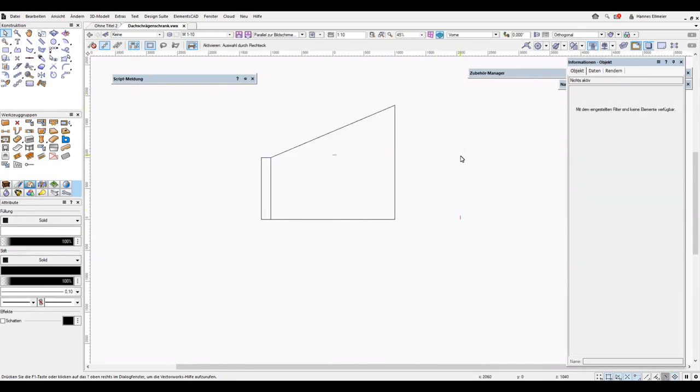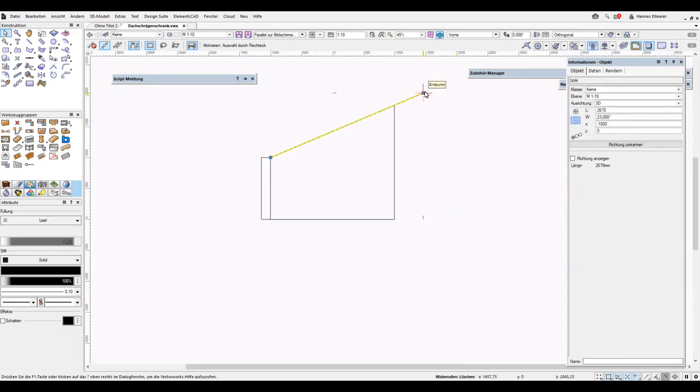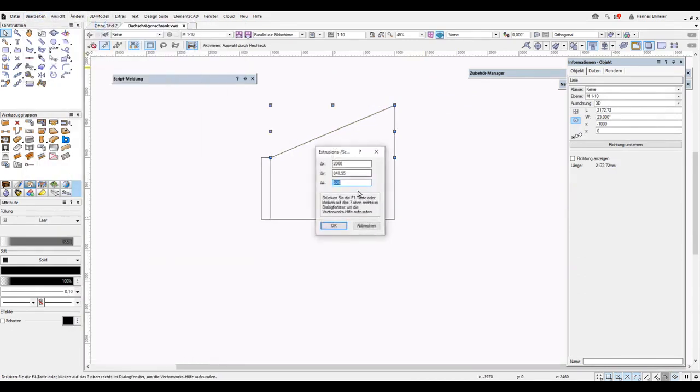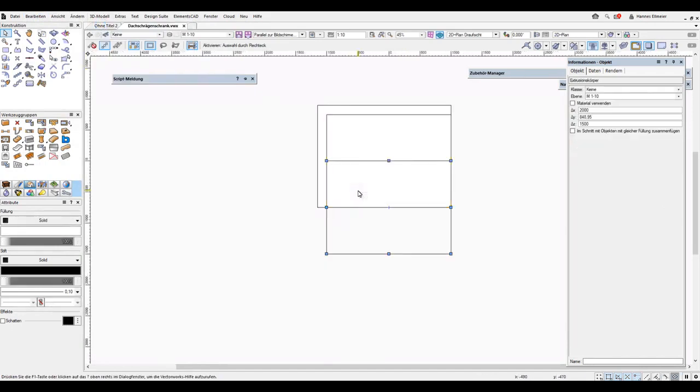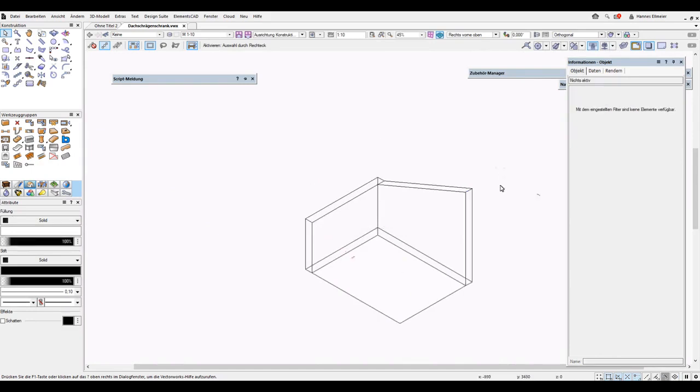Now, looking from the right front top. For the ceiling area, we could actually use this line to create it. That would be one option if I simply extrude it by 1500, then in the floor plan view I just need to move this surface to the corner, and I already have the final result.